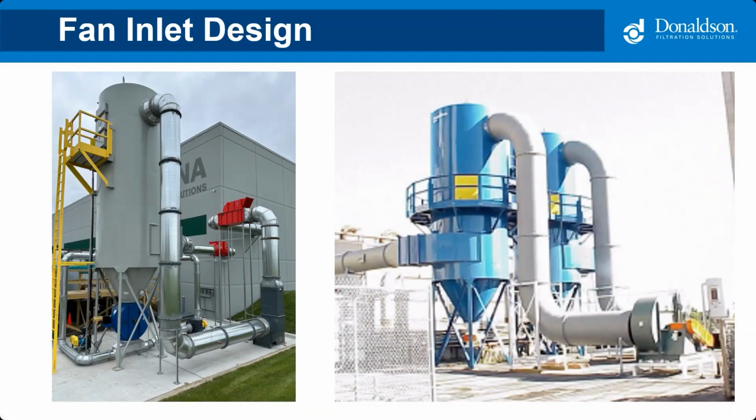As long, there's rules of thumb, 6, 8, 10, 12 duct diameters of straight duct in front of the fan. The more the better is what we really want to see. The one on the right there, here we got a giant fan with a large dust collection system. It's a little bit compromised that we've got a shorter run of straight duct into the fan, but real estate's expensive and do the best we can.